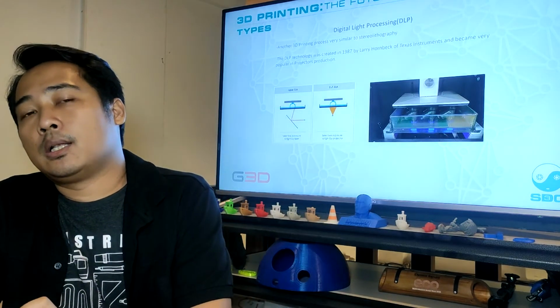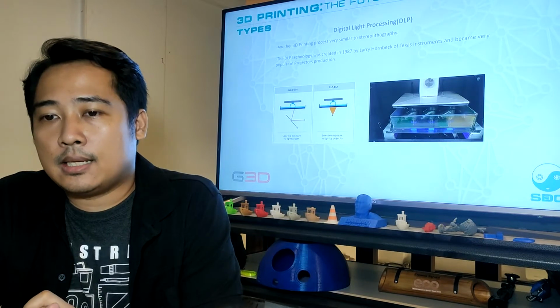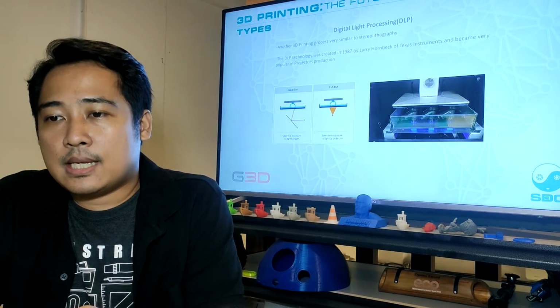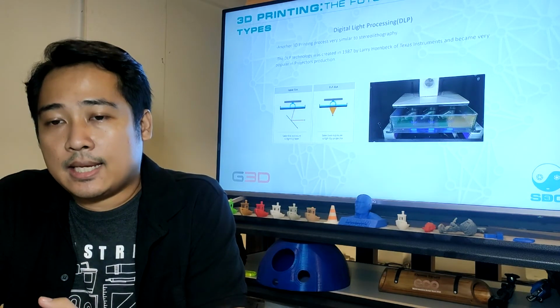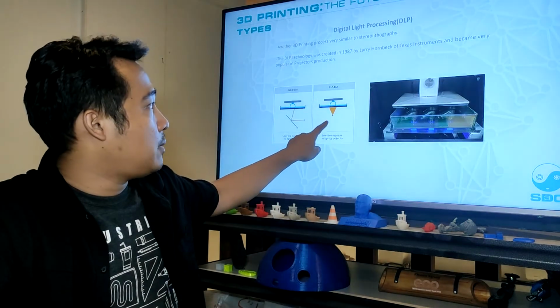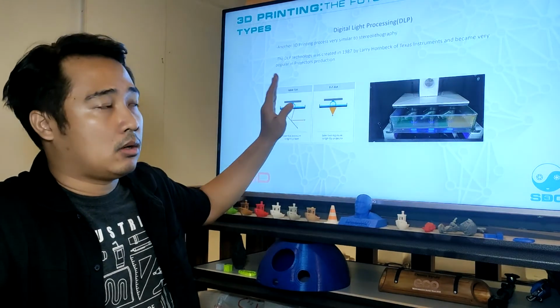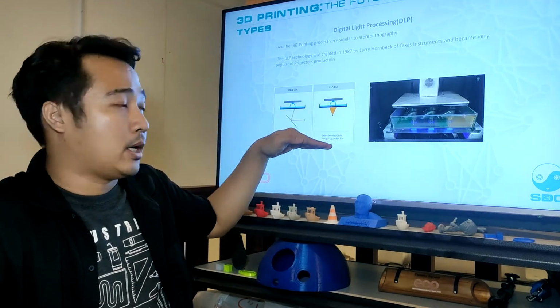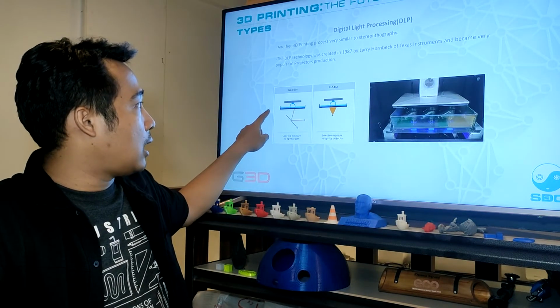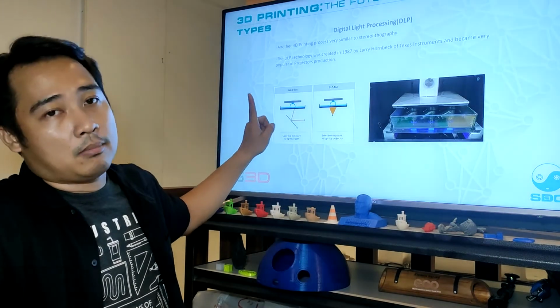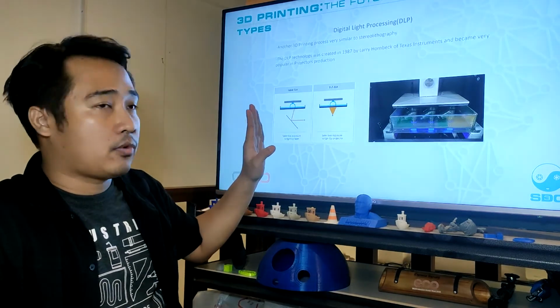So for 3D printing, DLP as well as SLA, they both use photopolymers or resins. But what makes SLA and DLP processes unlike is a different source of light. As you can see in this image, the DLP can print the whole layer, while the SLA needs to use selective exposure of light by the laser on each form or side.